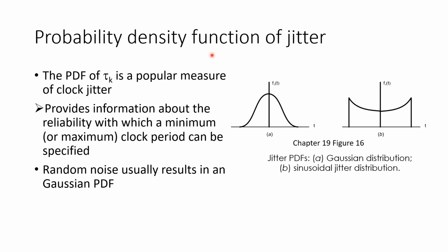A really important example of when we might be even more interested in this PDF of jitter than we are in its phase noise is if we imagine using the clock waveform to clock some digital logic circuits. In such cases, we have to allow enough time for the logic values to propagate through some logic gates before a neighboring clock edge arrives. So we're often interested in what's the earliest, the absolute earliest when we can expect the next clock edge to arrive.